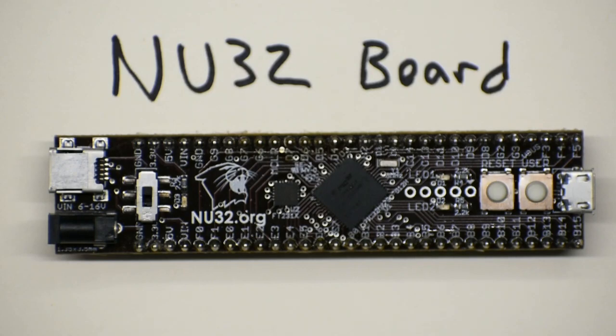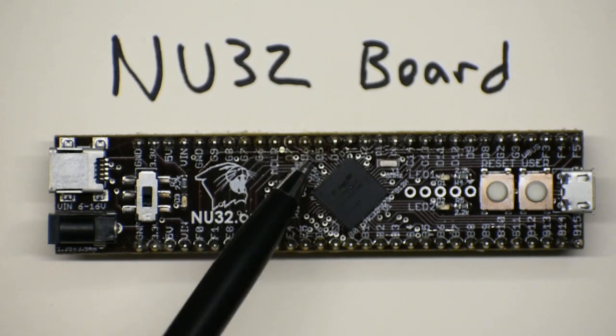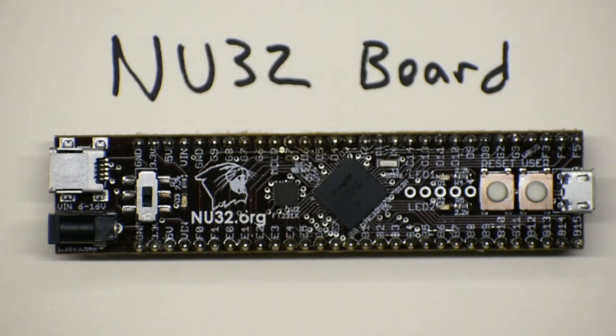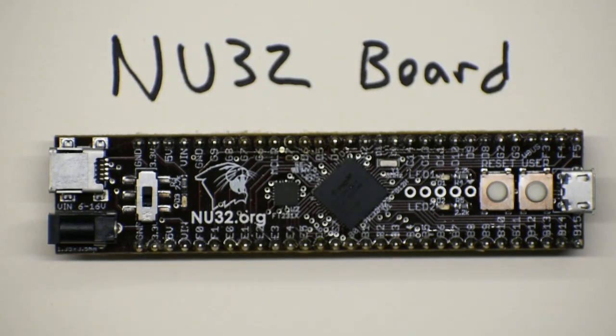So we'll write our code on our computer. We will cross-compile it, so that is compile it on our computer, but for a different CPU. So the code we compile on our computer wouldn't run on the computer. It can only run on this board. We will download the executable onto this board, and then when it runs, that's the only thing that runs. So it will actually be able to read the voltages on these pins digitally, perhaps several million times per second. So it can actually do things much faster than your computer because it doesn't have anything in the background that it has to worry about.